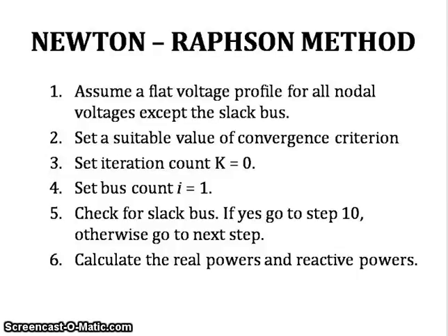Hello everyone. As discussed in the earlier videos, we were discussing load flow problems. The load flow problem is to find the steady state solution of a power system. The main output of this load flow solution would be finding the magnitude and phase angles of the load bus voltages, reactive powers at generator buses, and real and reactive power flow in transmission lines. If you want to increase load, whether it is possible or not.